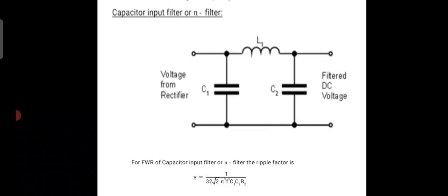Finally, we are going to obtain only the DC signal at the load resistance. I think the action of charging and discharging has been explained in the last circuit. Hence, there will be an output. The output will contain only DC signal, as the AC signals have been absorbed completely in the pi section filter.